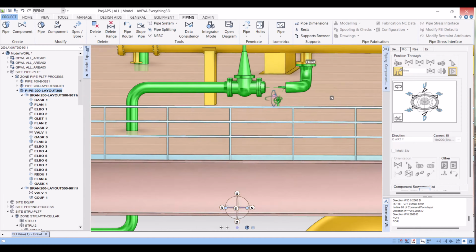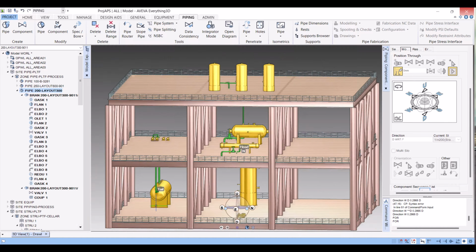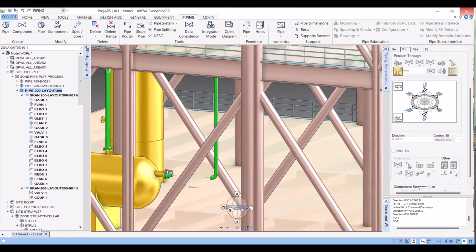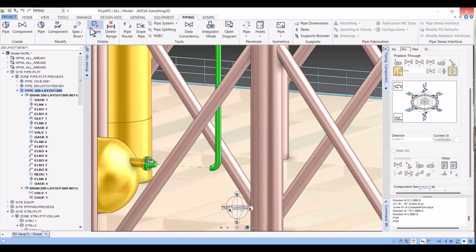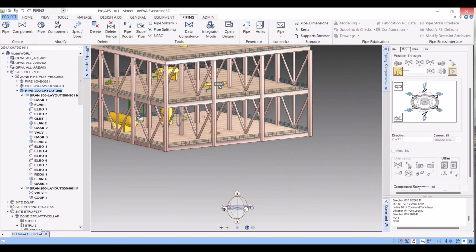I have one branch here which is disconnected, and the end point is also disconnected by providing the slope from the utility of E3D. So we will give slope manually, which is much easier and faster. So I will move this back.